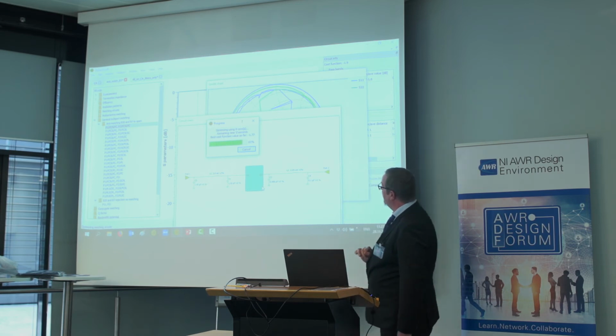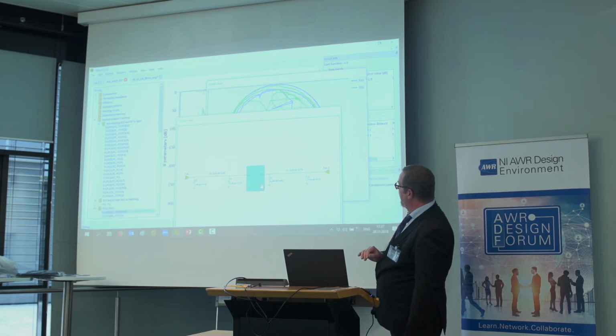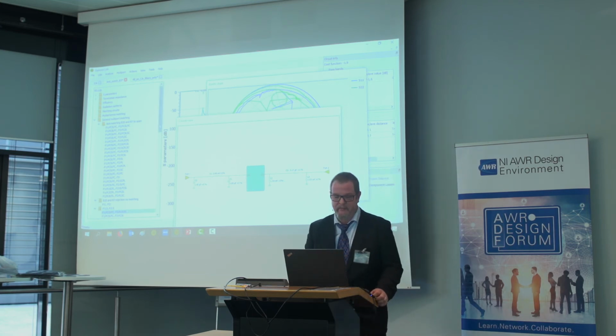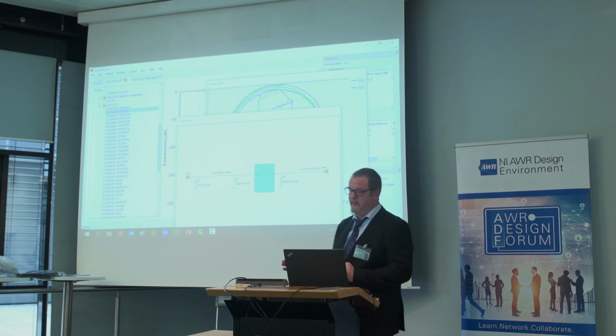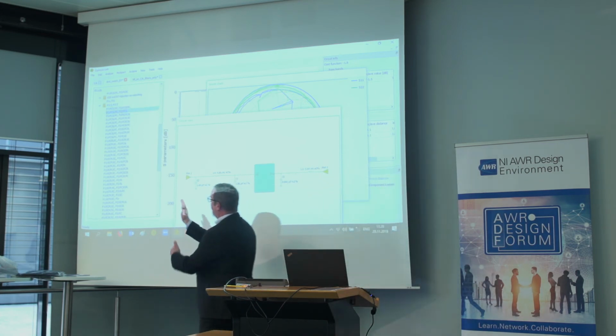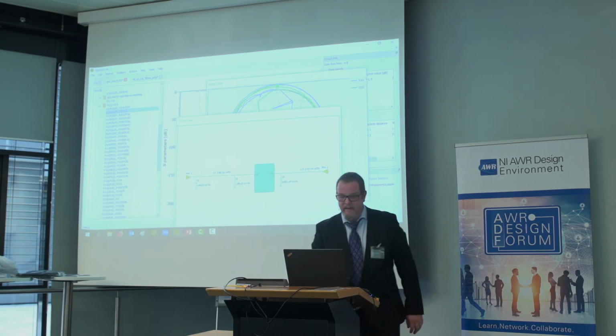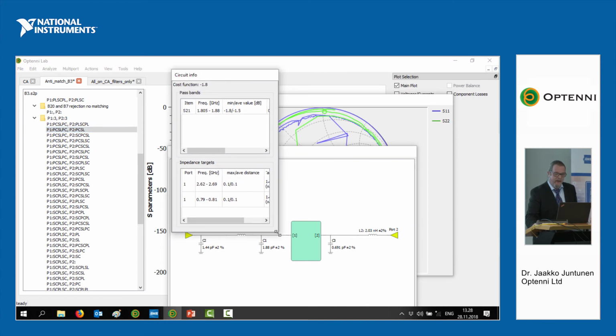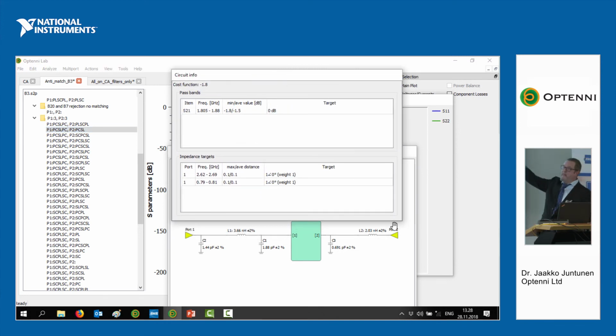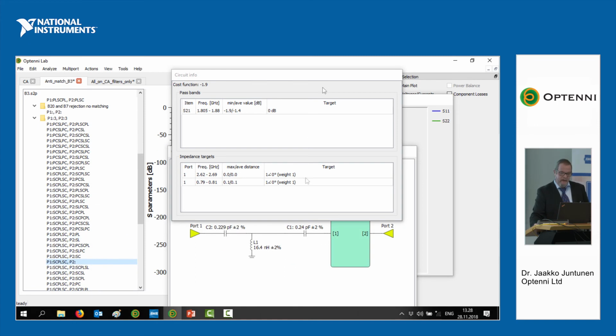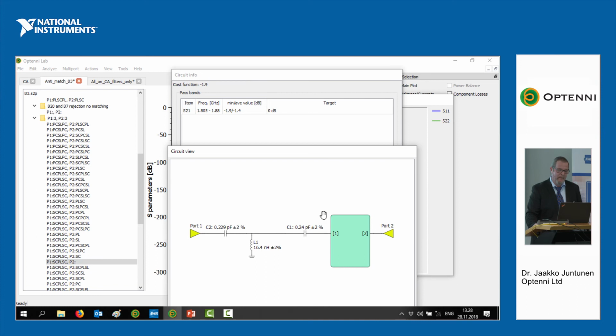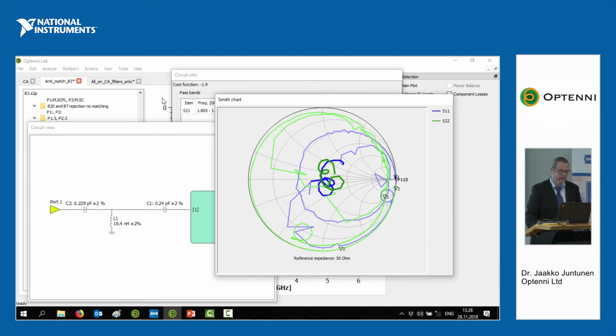And we can monitor the best cost function value so far. Then we get a ranked list where we can, let's say, pick the shorter ones, with fewer components. Of course they are not in the same measure, the insertion loss and the impedance target, but there is a combined cost function value, and we can notice that this very simple circuit here has a pretty nice cost function, about as good as the top performing ones. And let's look at the S11 only.